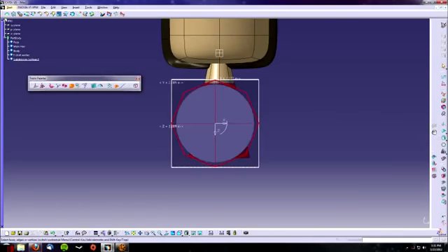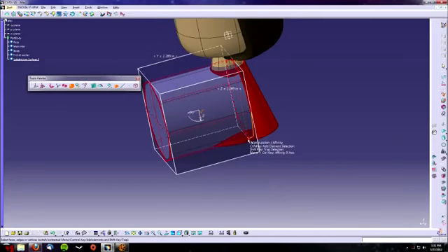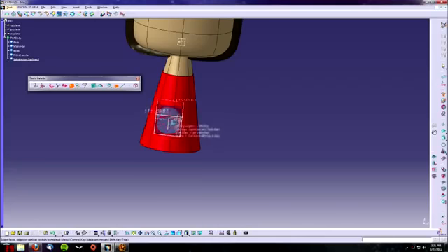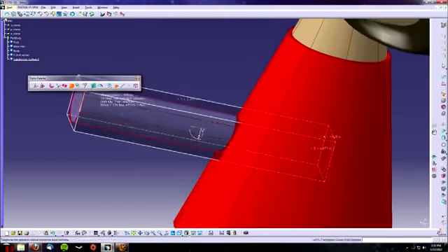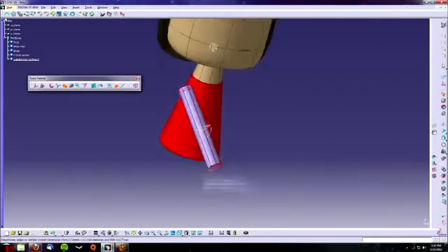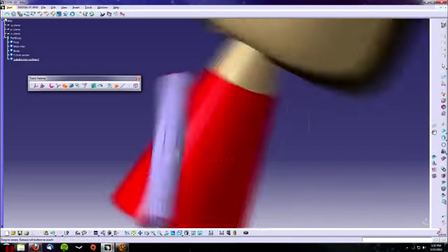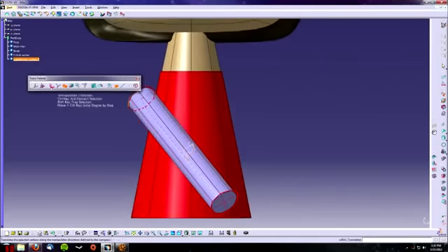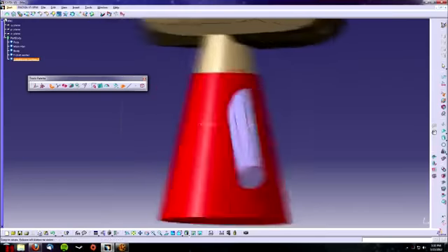Next, we're actually going to create his sleeves. To do that, we're going to use, you guessed it, another cylinder. And then we'll use the affinity command to size it down. And then we'll actually rotate and translate it to where his sleeve's roughly about 45 degrees from his side. Just put it where you normally would put his shoulder, okay? So sticking out 45 degrees out, and then you can actually use the translation command to move it into his body so it's at the appropriate length.